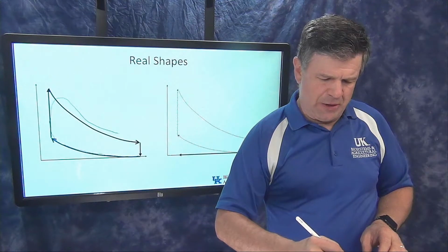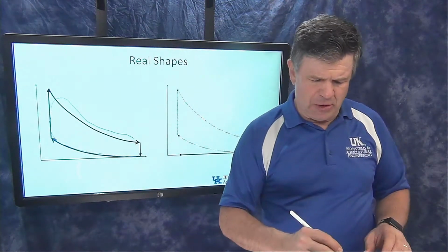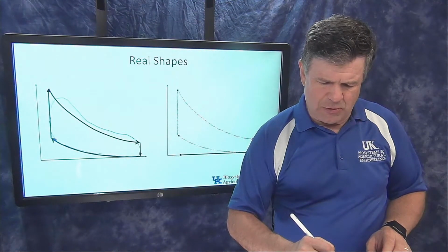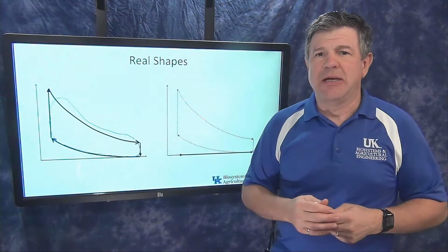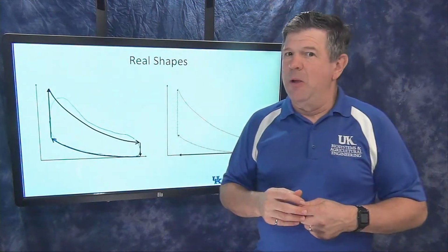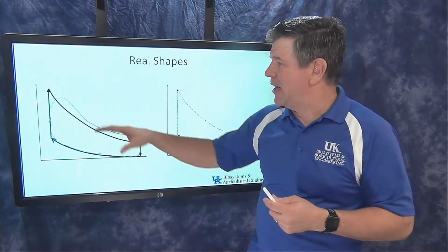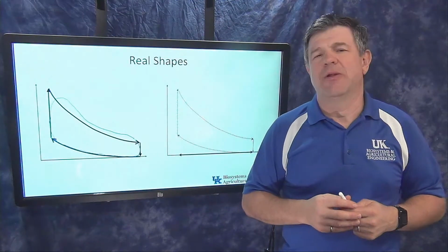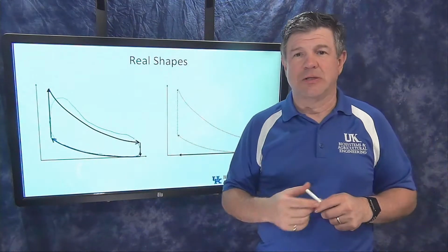And then when I open the exhaust valves down on this end, remember I opened that exhaust valve a little bit early, so I'm going to see that pressure start to drop. It's going to round off, hit this corner back here, and then start back up. So same basic shape, same idea, but now this is kind of reality. And again, that's what engineers look really hard at: all right, what's really going on in there? How can I change that? How can I make those pressures bigger and redesign engines, redesign components, all that kind of stuff, different fuels. Those are some of the questions that we ask there, but that's what it looks like, okay?